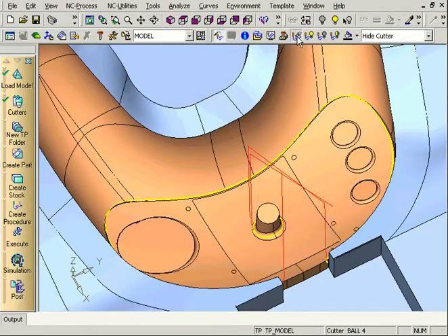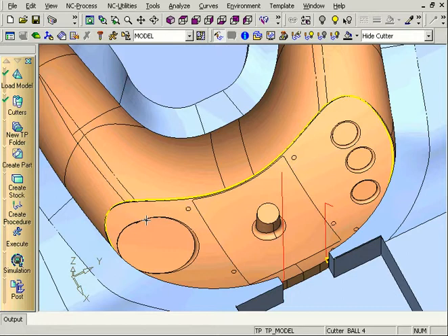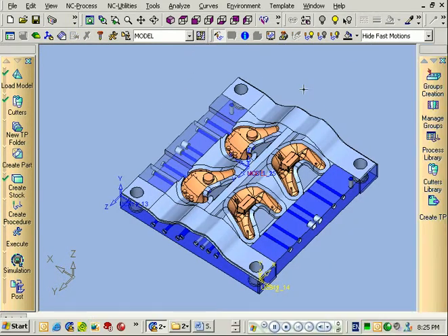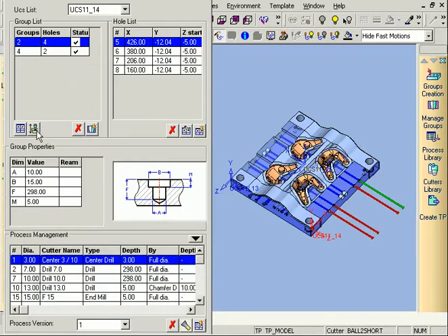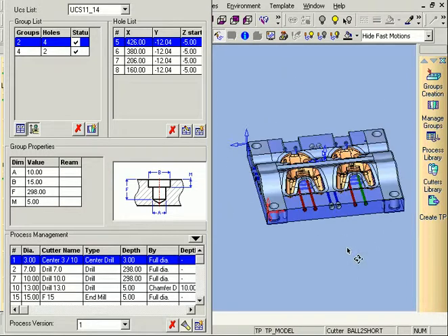If required, the user can modify toolpath motions directly without the need for rerun to recalculate. Here, pencil machining of the small boss in the center is cut. The application identifies hole shapes, assigns suitable cutters, and defines drill properties, including the XY location of each hole and the drilling process. Auto search is also provided and offers close value alternatives for missing tools.